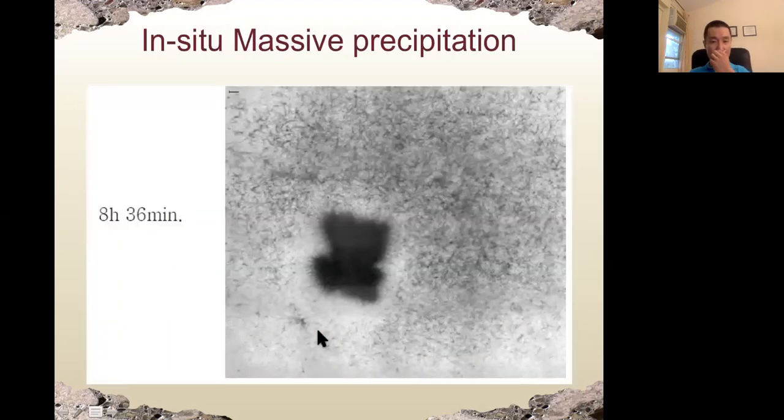All right, so this is an SEM picture, a scanning electron microscope image, of hydration product. This is at 8 hours. We can see in situ mass precipitation. That means the black area is the cement grain. If you pay attention to the outside, you can see needle-like hydration product generated around the cement grain. And also in the solution, we have more and more hydration product generated.